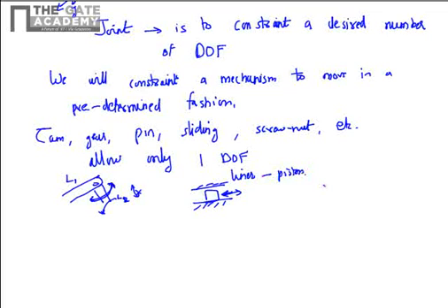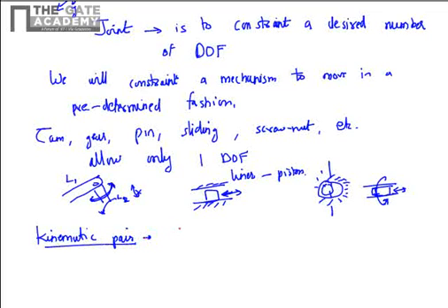However, it can be arranged in some other manner, like you have a cylindrical surface of contact, an outer surface and an inner cylinder. So the cylinder, if you see the cross section, it may have a linear degree of freedom also, it may have a rotational degree of freedom also. So it depends how we are forming the joint, what degrees of freedom you are willing to allow. That is why we classify a kinematic pair, which is nothing but two links joined by a joint that I just described, by degree of freedom.